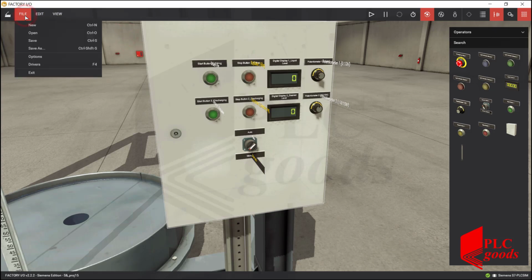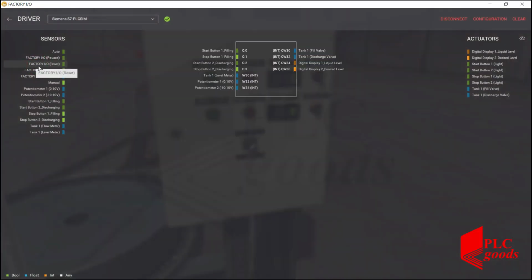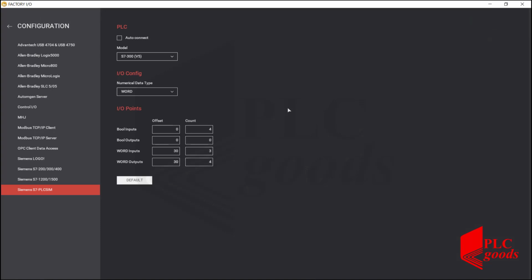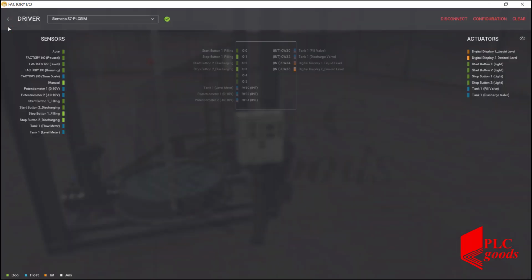Now let's modify the connection settings. I need two new digital inputs for the inserted selector. After that, I'll open the symbols table in SIMATIC Manager and define two tags for the two new digital inputs, I0.4 and I0.5.